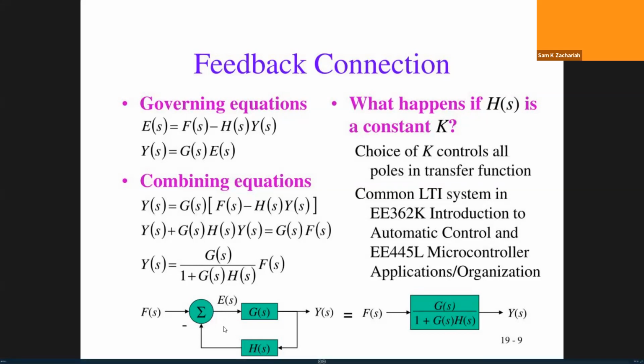So an ideal op-amp has infinite input impedance and zero output impedance. Because of that, whatever voltage you are giving to the op-amp, it will not take any input current, and whatever current you are taking from the op-amp will not drop any output voltage.